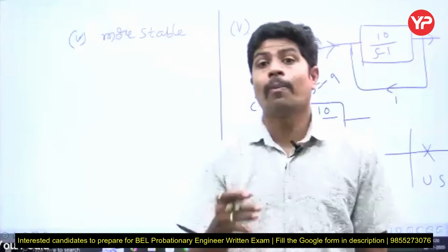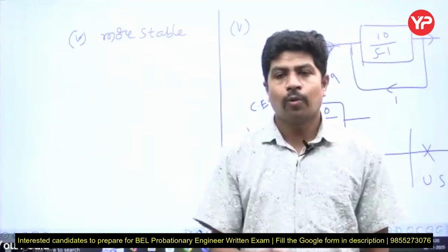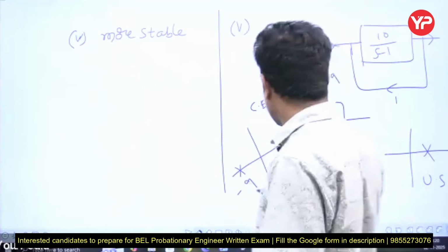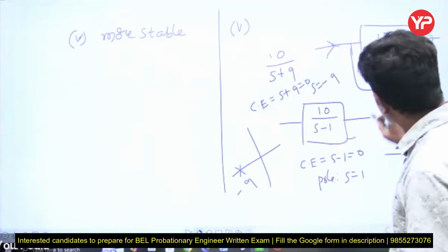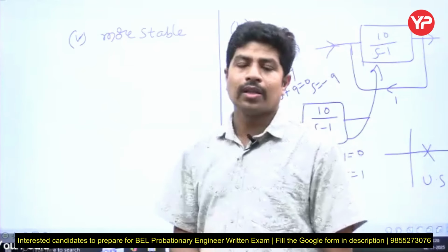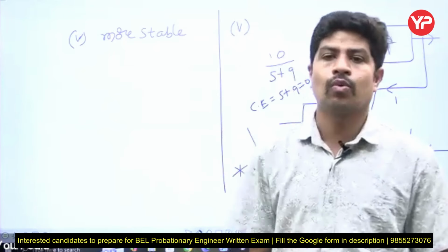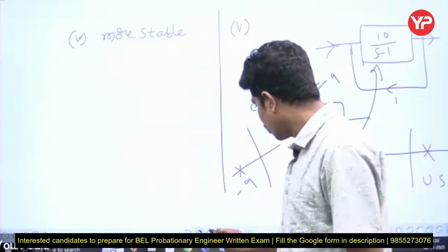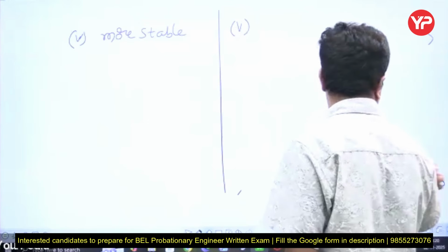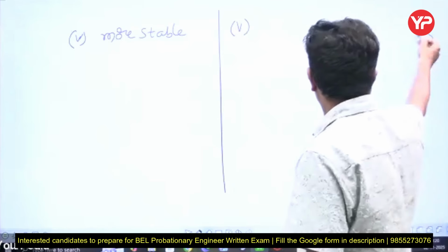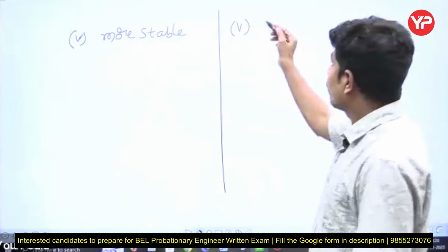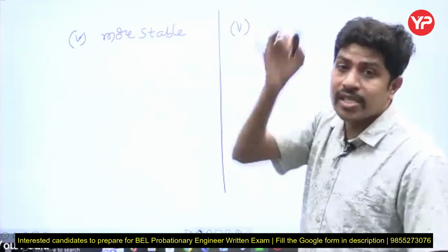That's what I am saying. If you properly apply, then no problem. If you are not applying properly, stability will reduce. So it means an unstable system became stable when you apply negative feedback, and that too properly, then its stability will be improved. I hope people are able to catch. But if a stable open loop system is there and you apply feedback, feedback may reduce the stability.